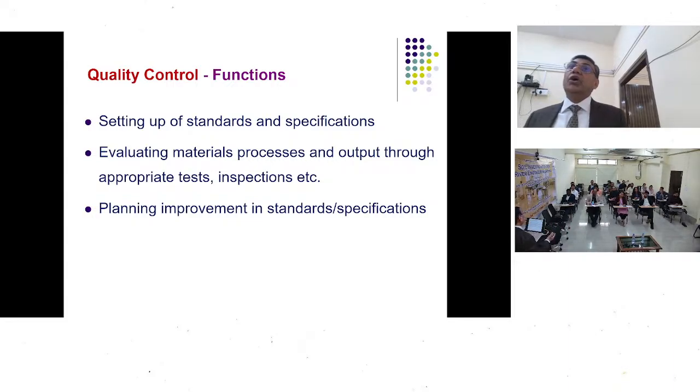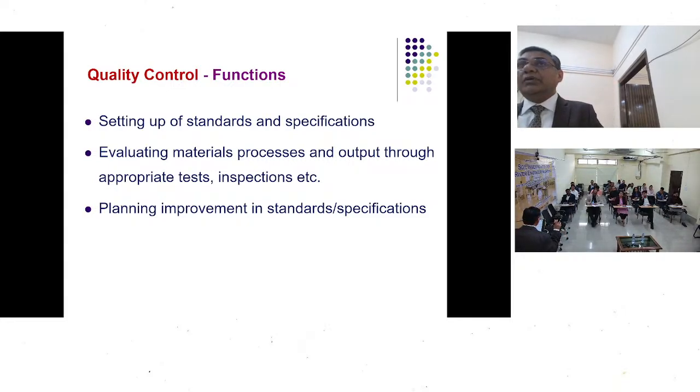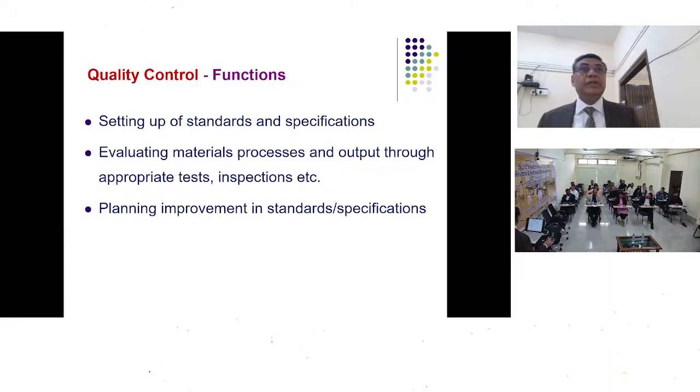Then you know what is the optimum moisture content which is required during construction. So you will see whether the contractor has calculated what amount of additional water is to be sprinkled on that material, and whether the method of sprinkling of that water on that borrow material is adequate or not. Is he taking proper care of that? That you have to see.